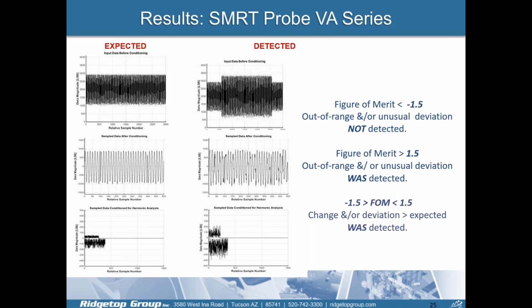We also know that in addition to instability oscillations, we get harmonic distortion. Instead of getting nice, relatively clean sine waves, we get something that looks like they're in the middle row on the far right. We process the signature in different manners, and our methods produce what we expect to look like on the lower left. That's what we expect. Because of instability and or harmonic distortion, we will get something that looks like the lower right-hand side. And so we're able to quantify those two values and say, well, this is larger in amplitude than we expect. Okay? And we do that for the 3 modes, and we come up with a composite figure of merit. And that's what makes it a very useful diagnostic tool, correct?